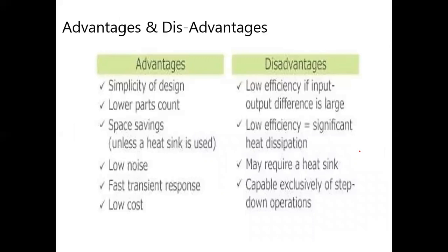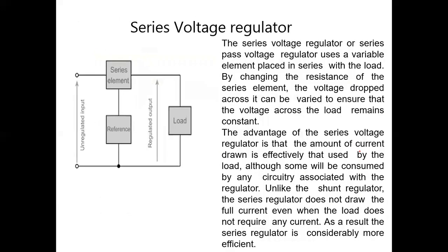So advantages and disadvantages of Zener diode. Advantages: simple design, low part count, low noise, low cost. Disadvantages: low efficiency, and more heat sinks are required. Next one is the series voltage regulator.